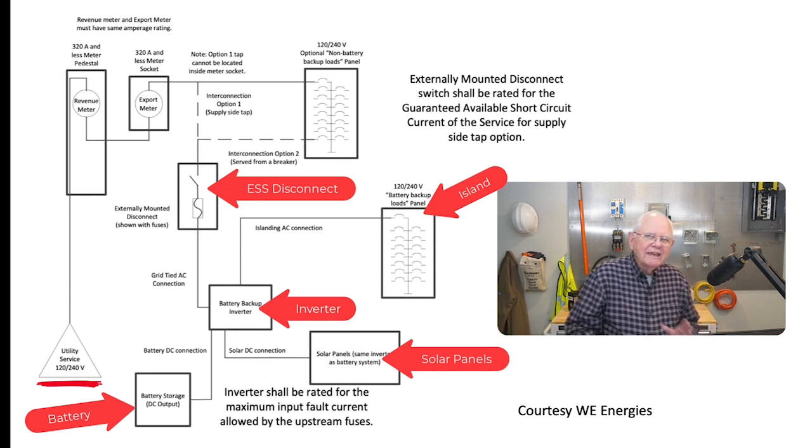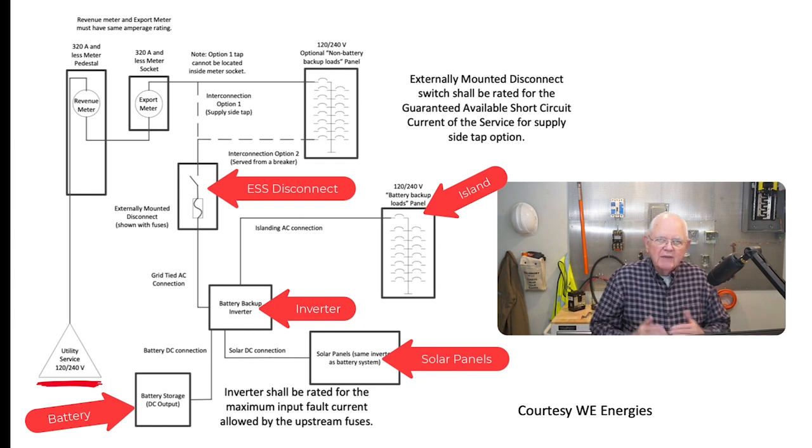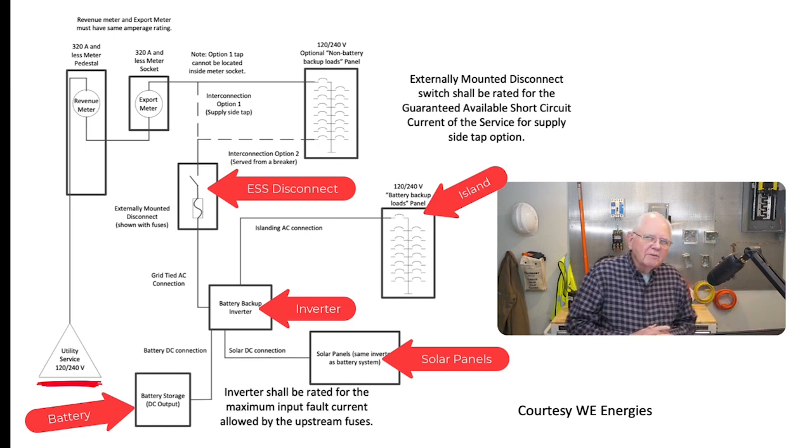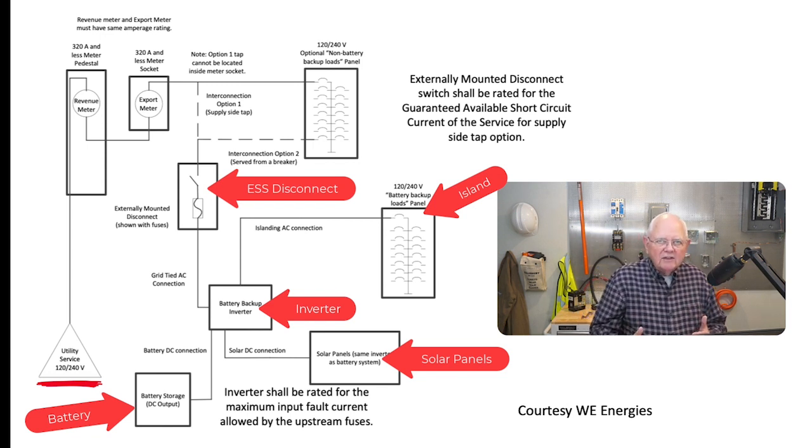What we mean by interactive inverter, and the definition is once again in Article 100, is that I can parallel it with other power sources, be it the primary power source from the utility or the power production network, I should say, at my own facility. That is what we talk about when you hear the term interactive inverter: I can parallel its AC output with other sources.